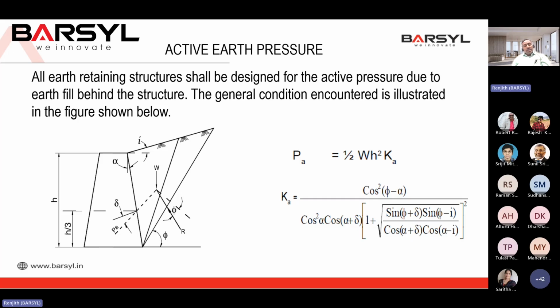The action will be like that only. Earth pressure will be exerting, and the abutment wall will be bending towards the traffic direction. So how much is the force? With W as the unit weight and H as the height, half W H squared multiplied by K, the coefficient of active earth pressure, will be the total force. The earth pressure diagram is clearly given in the IRS bridge rules and in the substructure code.